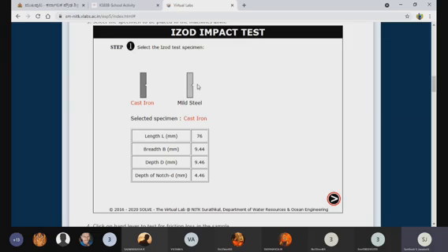Then take a hacksaw blade and create the groove. Groove depth will be 2 mm. Keep it in your mind; in the practical examination they can definitely ask you what the groove depth is. The groove depth will be 2 mm, right? From here to here is 25, and the rest will be inside or below. Sorry, it is 50 plus 25 is 75. So the groove depth will be 2 mm.